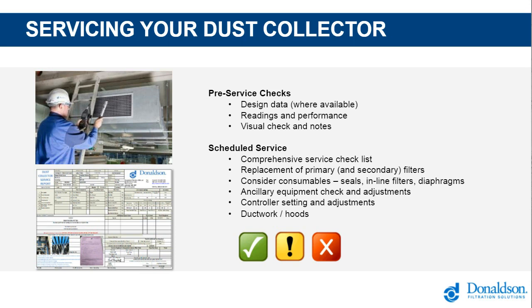In addition to replacing those primary filters and secondary filters where they're fitted, consider all the other consumables. It's really important that when you change out the filters, they're all replaced at the same time, as I mentioned. Ensure the filter seals are in good condition and that the sealing surfaces are thoroughly cleaned. This is a really important part, and it makes sure that you've got that effective seal and barrier between the dirty air side and the clean air side of the filter.